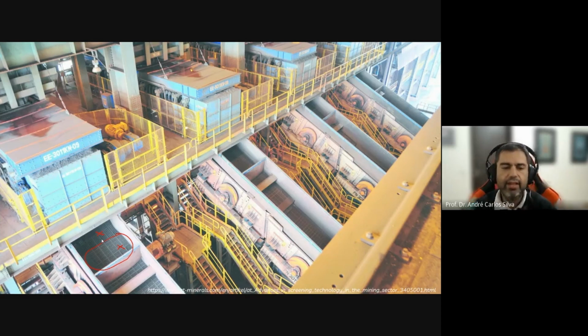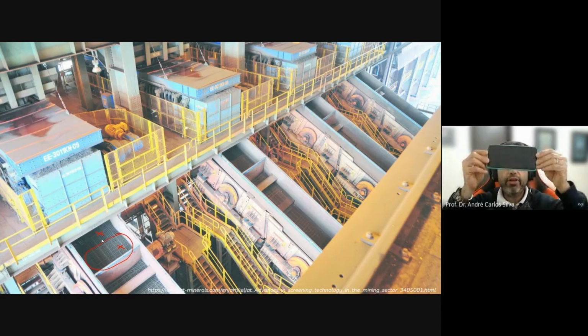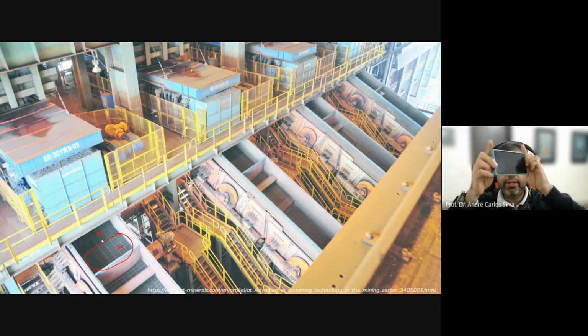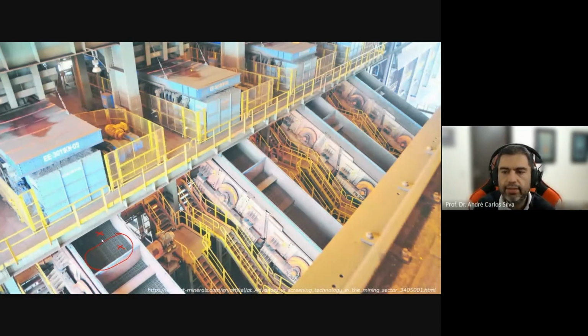How do we do this? Let's consider this cell phone, for example, okay? If I show you the cell phone like this, you're going to see this as the aperture of the cell phone. But if I incline my cell phone, you're going to see a different aperture for the same phone, okay? So at the beginning, we have a high inclination. Then I move on, and I'm going to do this with the panel. The panel is changing. So I change the size of the aperture in here to balance the inclination of the panel. So the projected aperture is always the same, okay?